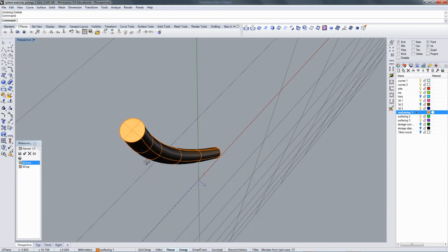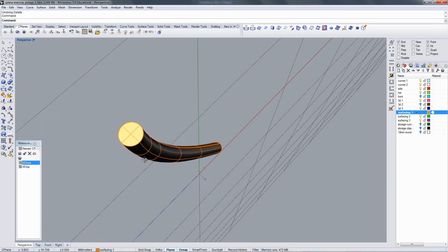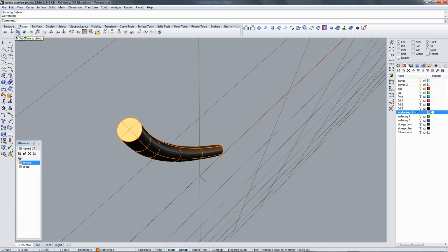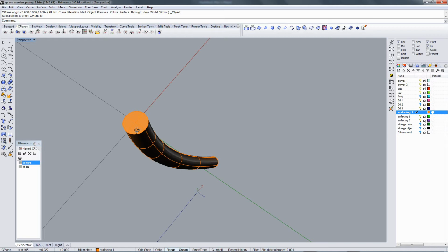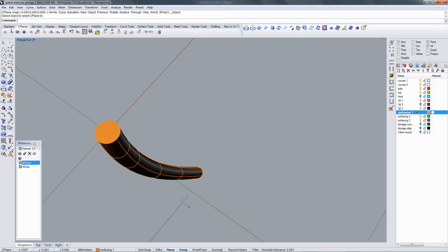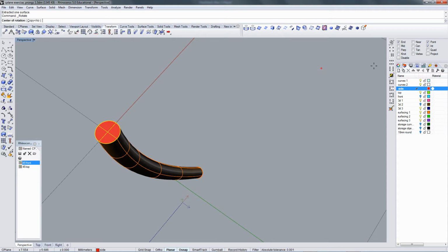Since I can't make it misbehave, I'm going to set it up to misbehave automatically, just so you have an example. Setting my C-plane here for now. Going to extract a surface, copy equals no. You do not need to do this with your work. If you're following along, just watch. Going to rotate that 45 degrees. And since it's a round prong, that will fit right back on.